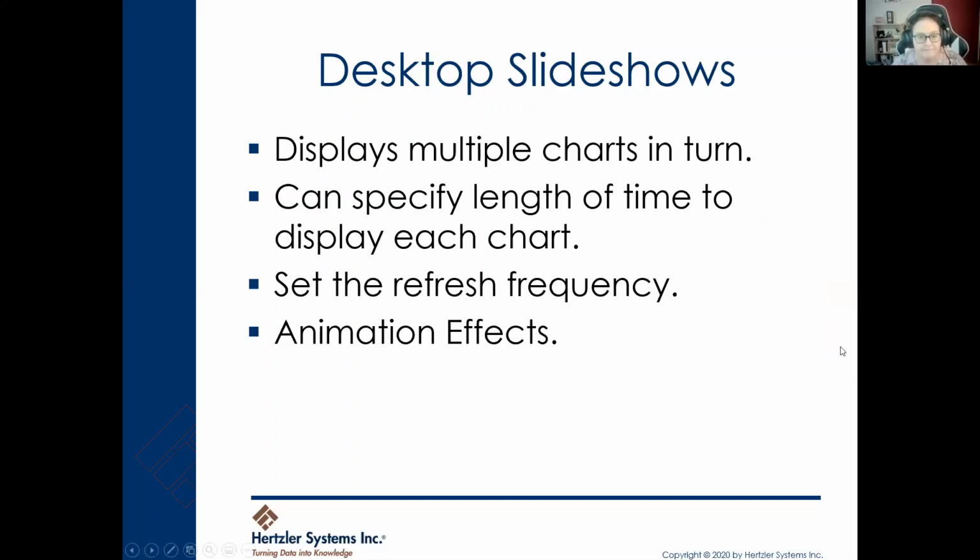The last key technology I really wanted to talk about, or next to last, is the desktop slideshow. This is something we've added in the last few years that allows you to take a desktop, or basically any charts that you have open in GainSeeker charts, and display them full size and cycle through them one at a time. Every single chart will be maximized within the GainSeeker charts window. It will be displayed for a certain length of time, and then it will switch on to the next chart. When you set up the slideshow, you can also specify how frequently we will go back to the database and check to see if there's more data that needs to be added to the current chart.